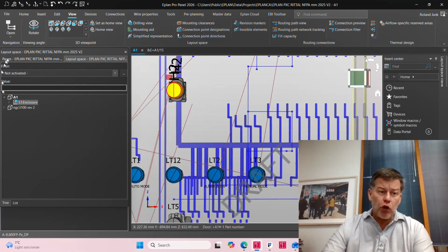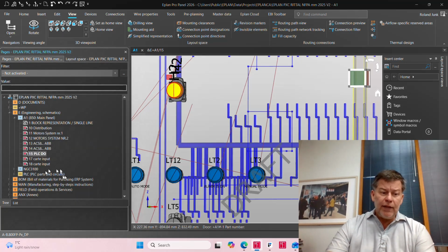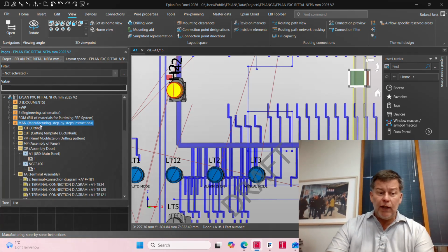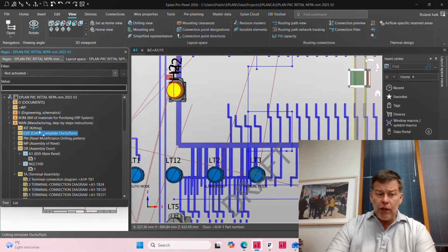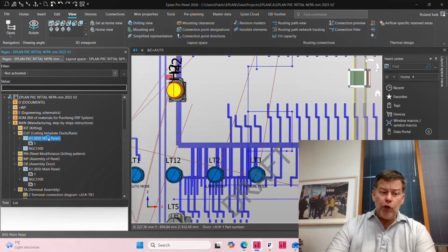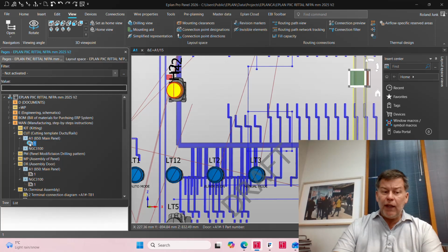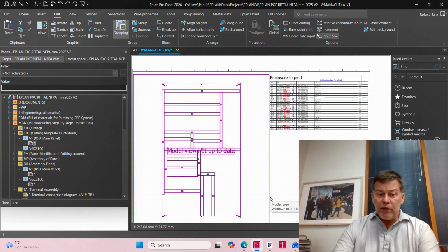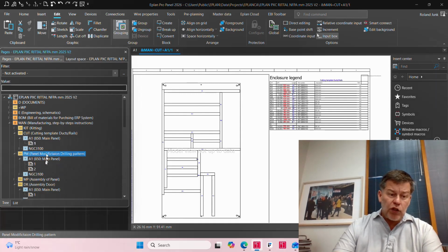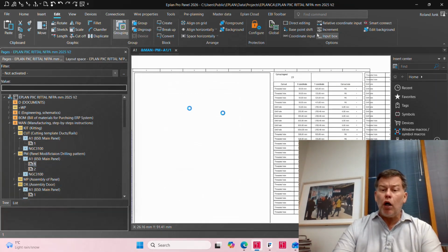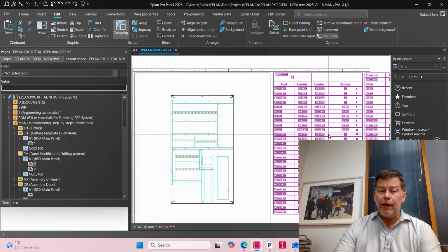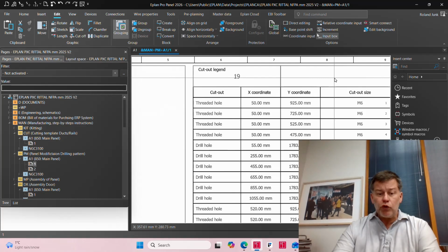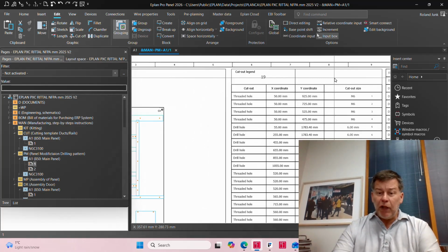Now, if you take the EPLAN Canadian template that we share with you, you have a section here that is, of course, for manufacturing. In this section here, the kitting, the cutting. Inside the cutting area here, if you actually drill in, you will see everything that is there to be cut, like ducts and rails. In this other section here for the drilling, we typically will show you all the drillings, and even with a detailed view of individual holes or threaded holes or shapes that have to be placed in certain areas.